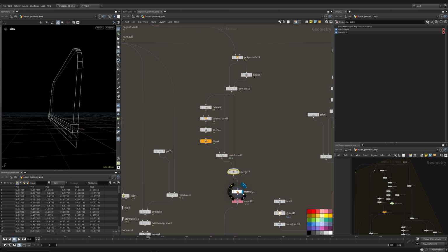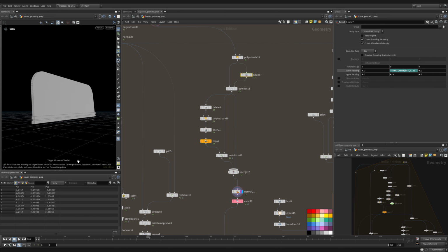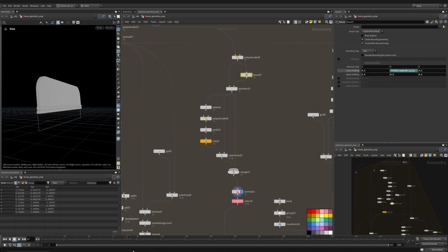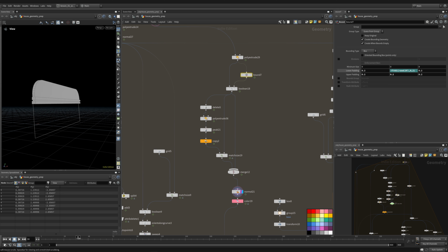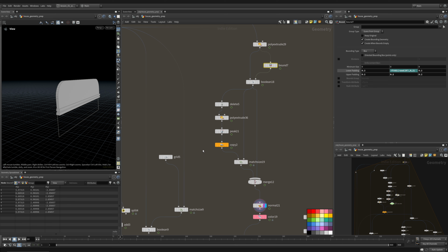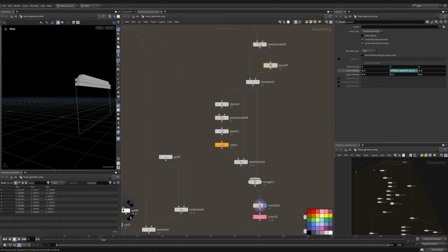So when I bring this normal in, this bound with the random lower padding will open and close the garage door random amounts. So it'll clip off little areas. Maybe it'll clip off 1 meter, 2 meters. And then it looks like for each house, maybe the doors are more open or more closed. But this was the solution I came up with for creating some variation between those. So not every garage door is the same height. They're not all open, they're not all closed. They're a little randomized.